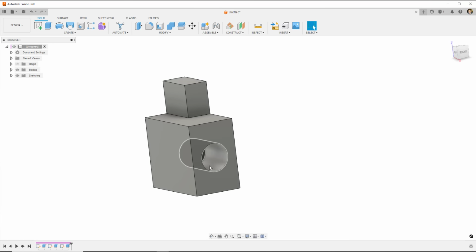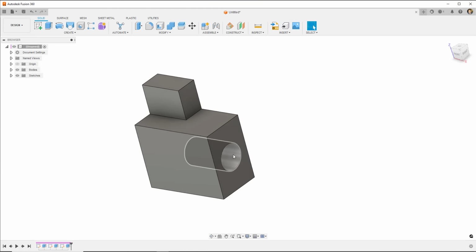When we put it as minus 100 millimeters, that worked, but if we then went back in our history and changed the length of this actual object to 150 millimeters, this extrusion would still be telling it to go back to minus 100. So then we'd have to have another process to update. We'd have to update something else. In Fusion, what you're trying to do is make everything tie together all the time.